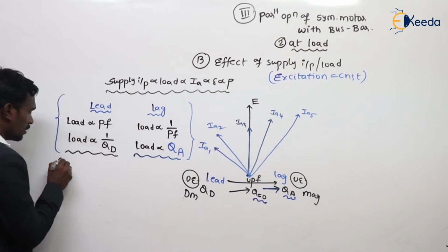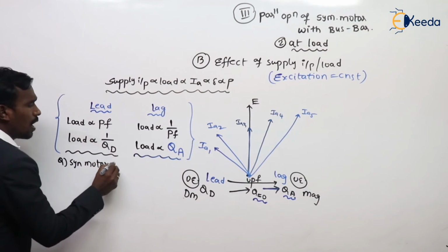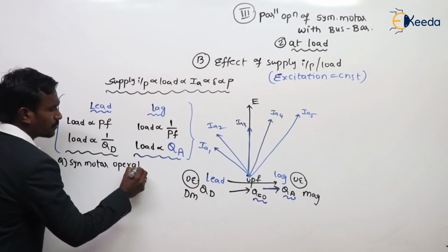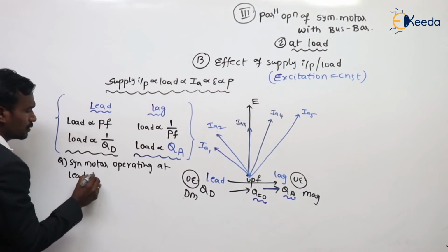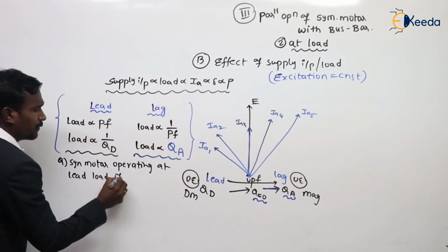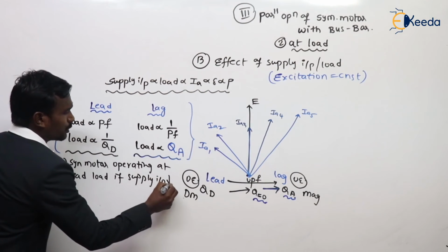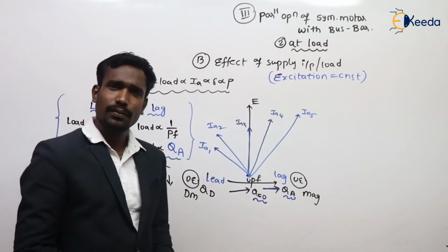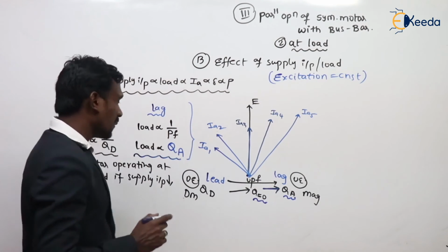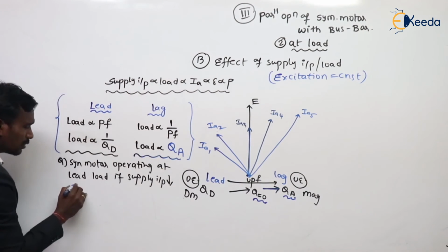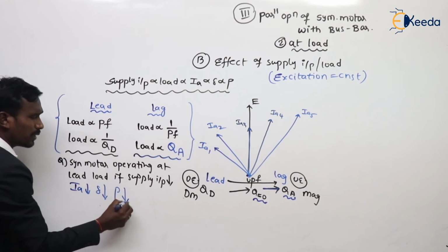For example, a question: synchronous motor operating at leading load, if supply input reduces, then what happened? When this supply input reduces, automatically Ia reduces, load angle reduces, power also reduces.